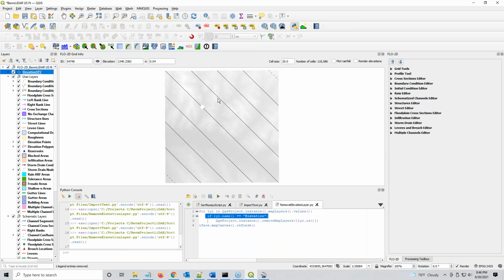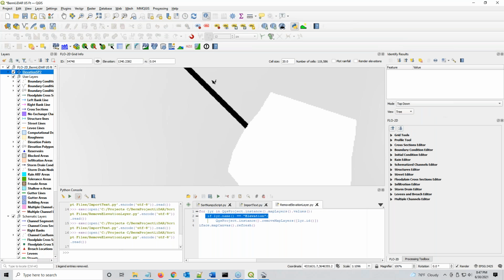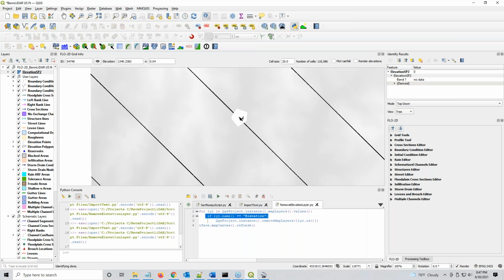But here's the deal with the LAStools and why it doesn't work well unless you purchase it: you get these diagonal lines through the file. Let's do a quick ID on them. They are 0 value. So that's not good for this. And as you can see,